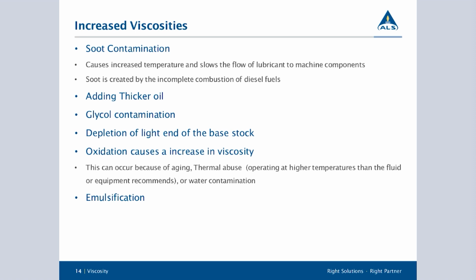So when you add a thicker oil in, you should see increased viscosities. Once again, you don't ever want to mix things together, because it starts to create scenarios where you're not sure if those oils are compatible. So you do want to make sure that you're topping off with either a compatible oil or an oil of the same grade or the same type. We do have tests here at ALS, run out of our Kansas City lab, should you desire to mix them, that can add more information to see if they're allowed to be mixed. But I definitely don't recommend just adding an oil that you're not familiar with into your system.